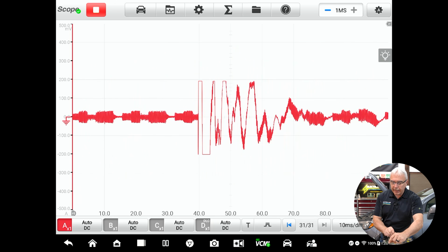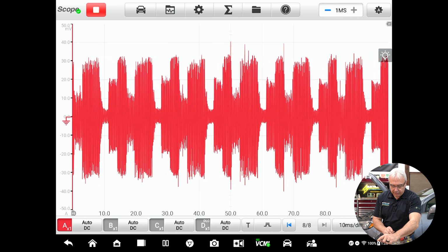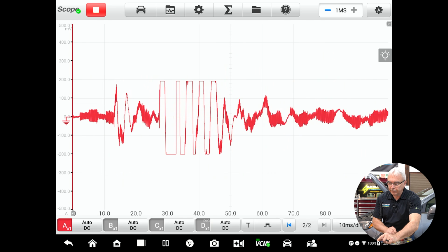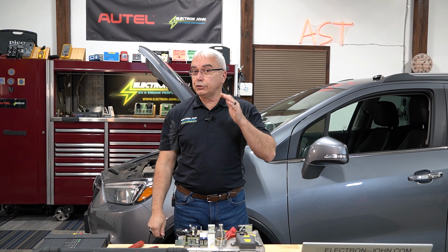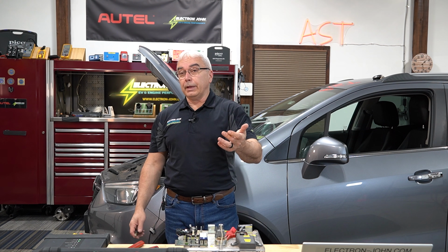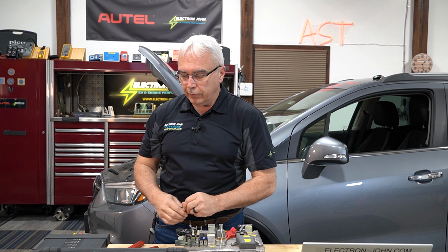But I'm going to go ahead again and tap on this. Nope, didn't hit freeze fast enough. And I froze the pattern on the screen. So anytime that there's noise on your engine, you would expect to see that type of pattern. Now, the louder the noise is, the taller and more frequent it is, so the amplitude and frequency is going to change in that pattern. And that's why the manufacturers use that to help determine when it's in startup mode. Because that starter motor engaging some teeth on a flywheel is a very noisy time.